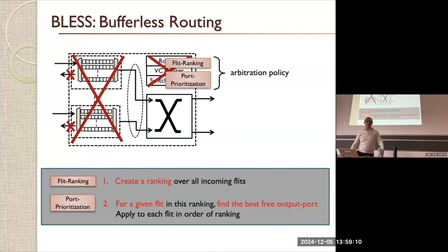So that's a good question, and the paper tackles two things. If you do flit level routing, if you use wormhole routing, what you said is true. But you could also have a flit and treat it essentially as a packet. The easiest way of implementing this is having small flits, but treating them as packets, meaning having source and destination information in them as well.